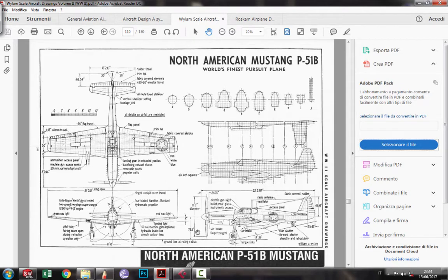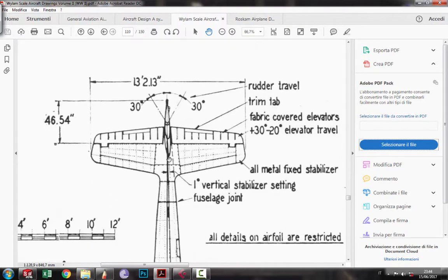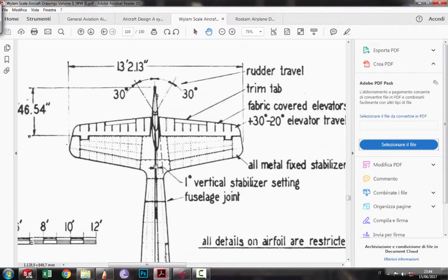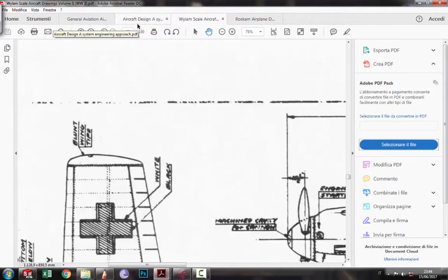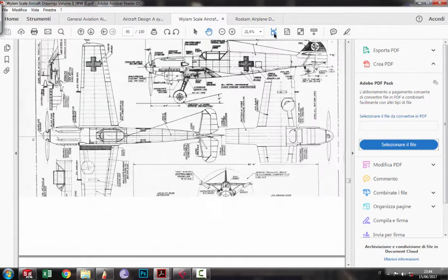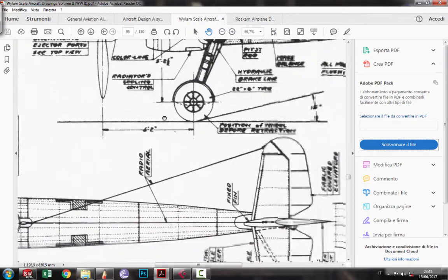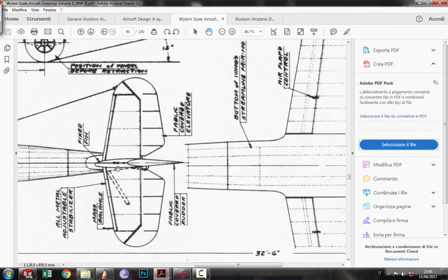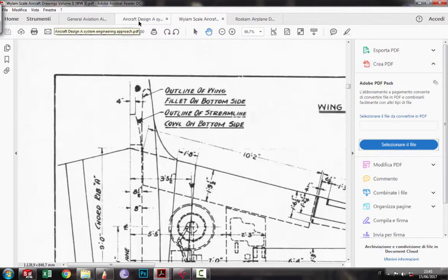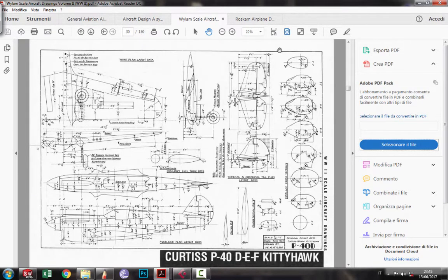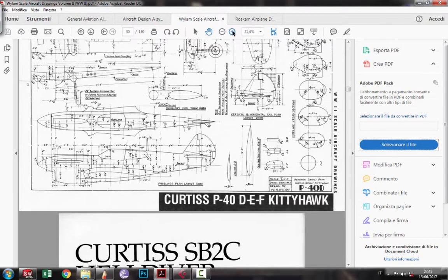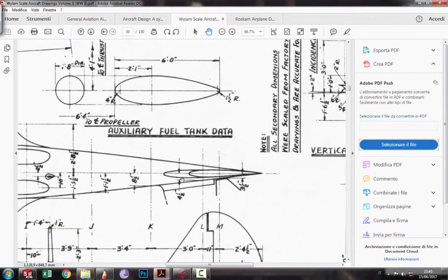Okay, so first of all, this is the P-51 Mustang, and as we can see here, the tail is not symmetrical, but has some camber and some offset angle. You can also check pictures of it on the internet. Everything is there; you just have to search for it. We have a Messerschmitt, and the root is not symmetrical either, but has some camber. And lastly, we have the P-40 Kittyhawk, with the same configuration. You see there is a camber, and it is not symmetrical.